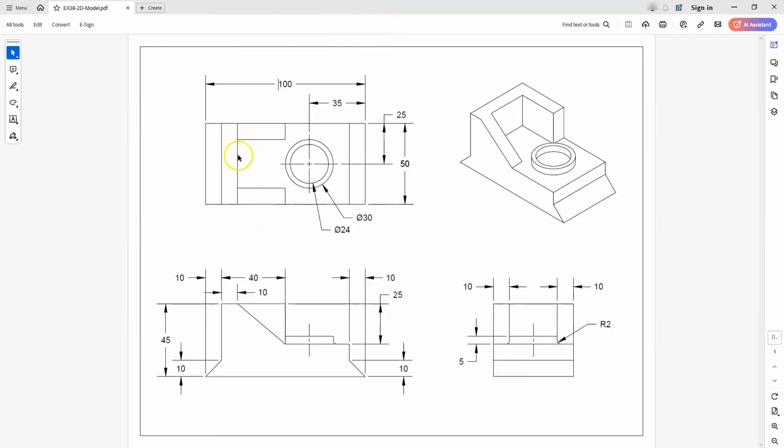So you can see here in the drawing that I took this line here and I offset it 40, when in reality I should have offset this line here going 40, because if we refer down to here, it's showing that this edge here is going to be 40 going this direction as opposed to this edge. And the first one that I made was just a simple typo. I typed in 60 instead of 50. But those are now corrected, and it's sometimes good to go back and look at things and know how to correct them without actually restarting your drawing.